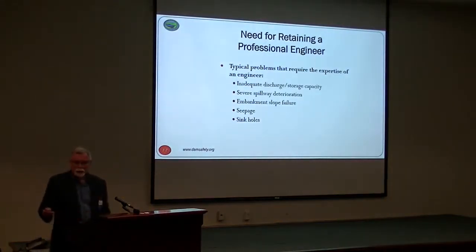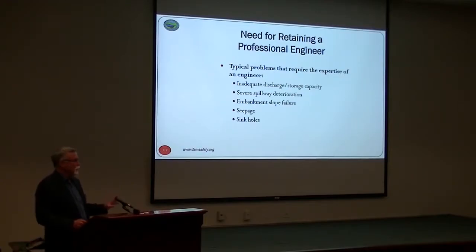When do you need an engineer? As DHEC said, it's not general maintenance, but when there's a repair or replacement or a major work like spillway capacity, slope failure, seepage, you need to get an engineer. And like if you got a seepage problem, you're going to get a geotechnical engineer. You're not going to get a structural engineer because it's not a structural problem. So sometimes, depending on the thing, you need to find an engineer that has the right experience with what problem you actually have.